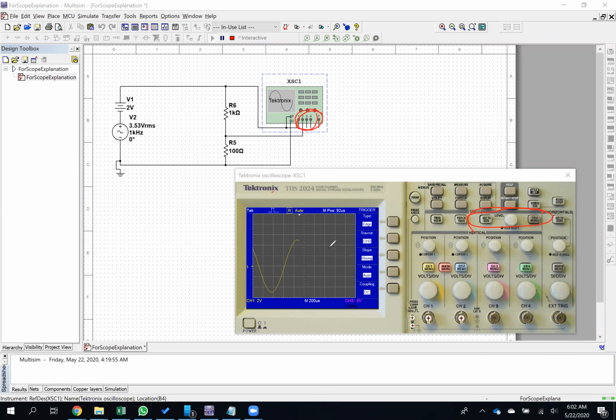So what I would do is put that source to my biggest waveform that's connected. So right now I've got it on channel 1. And sometimes the trigger level, I'm turning the trigger level wheel, and you can see, I'm going to circle it for a second, this little tiny arrow moving up and down, that's the trigger level.